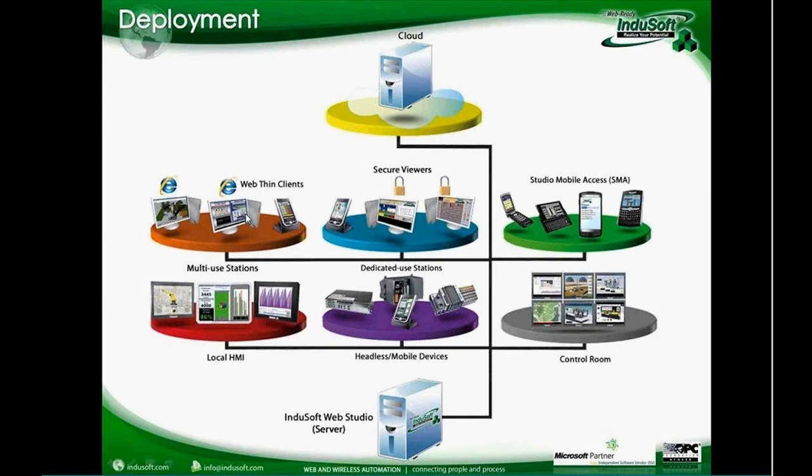They are the thin client stations. The web thin client stations is where you use a web browser, Internet Explorer, to visualize the application, from a regular PC, an embedded device, or even PDAs and cell phones running Windows CE Mobile 6.5.